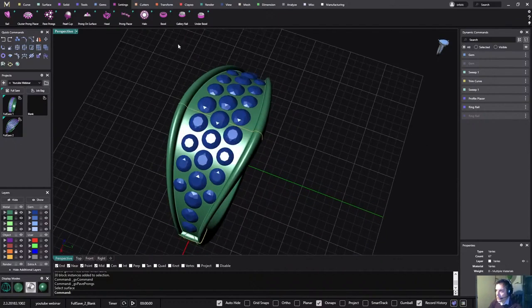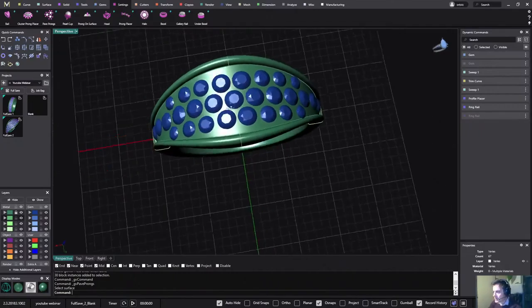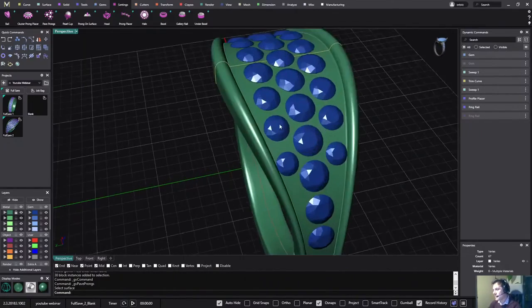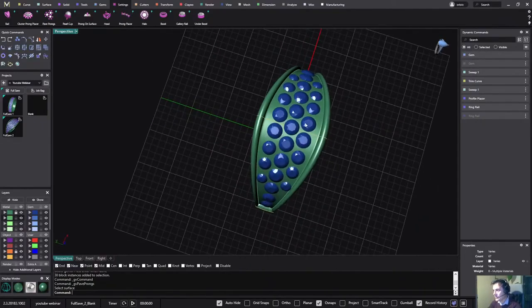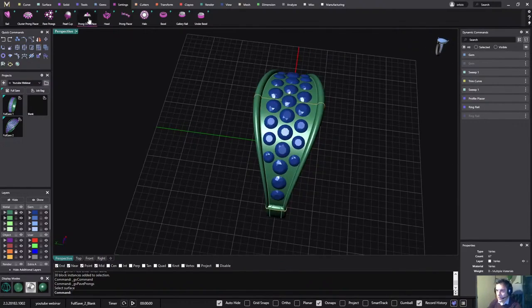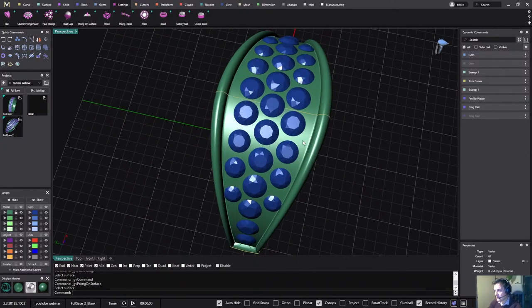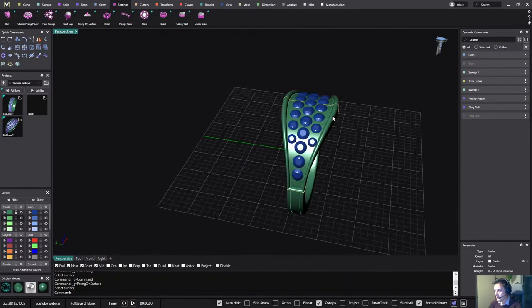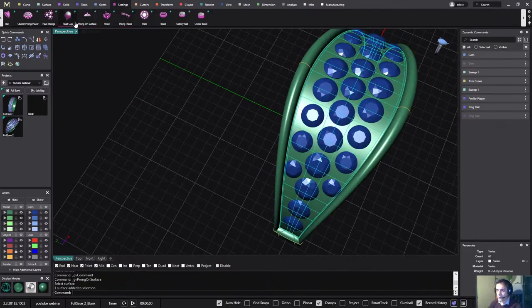The only thing that you need to do is go to the gems on surface, use the different mirrors, and when you are using the different mirrors, then you go super fast to place all these stones, and all of them have the same distance, so then it's very easy to place prongs at any time. So I will be able also to go on the prong on surface. Let me select this surface. So I can show you another tool, prong on surface.